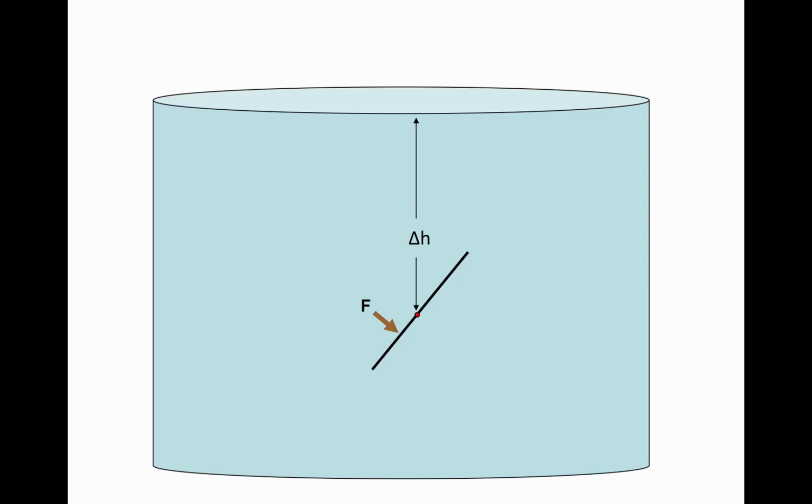Okay, so F is still the hydrostatic force like it was before. You can see the red dot identifies the centroid, so that's the center of area for the gate. And the centroid for the gate doesn't change whether it's vertically oriented, at an incline, or horizontal. As long as that gate is fully submerged, the applicable centroid stays the same on the gate.